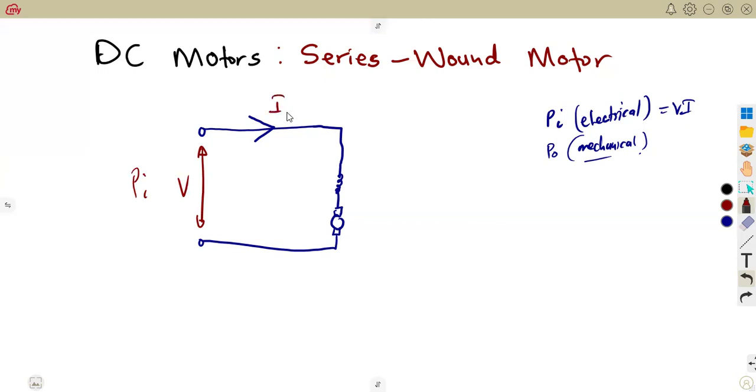This is our load current. To the series field, where we have got the series resistance as we had before, the current is flowing into, take note, into like this. So meaning to say we're going to have the current in the series field, that one which is going to flow into the armature, referred as our armature current, that's having the generated EMF, which is the one that we call the back EMF, as you are to consider a motor,